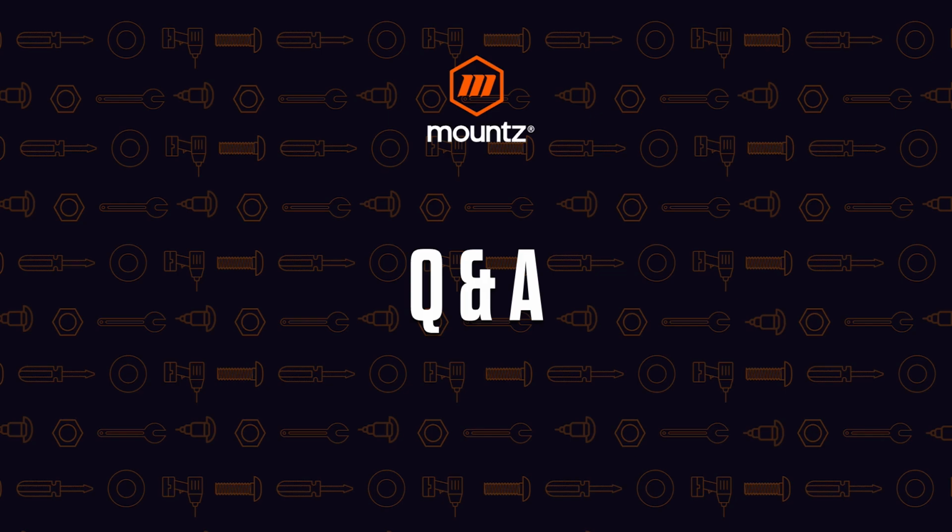All right, Dave. Last question we have is: once a fastener or bolt's been tightened and it's been, say, removed, can it be reused for another tightening application, or should it be discarded with a new fastener used? Typically, you could reuse it if you haven't moved past the yield point, as we talked about at the beginning of the presentation.